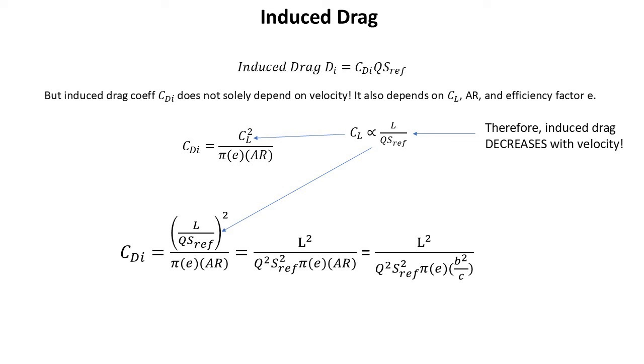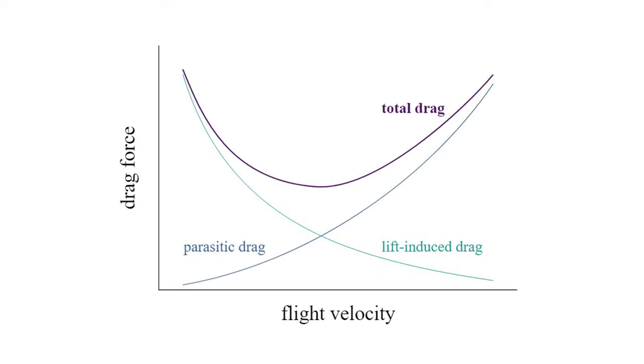I've also reviewed the wing efficiency factor in the first video in the series. What's important to know here is if we purely want to maximize this efficiency factor and decrease induced drag, elliptical wing loading, where the lift force is the greatest at the root and decreases towards the tip in a manner that follows the equation of an ellipse, should be sought after.